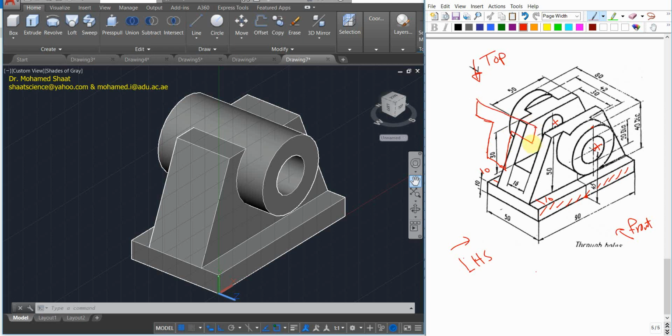And this T-shape, if you extrude it, it will be extended all the way this way. Okay, like you have a T-shape and you're gonna extrude it, so you're gonna find it intersecting with the shape, then you're gonna subtract. Okay, as you can see, this requires more practice to come up with this shape, to come up with these things, right? So this T-shape, it should have this baseline. It should be 16, and this height, it should be 30.